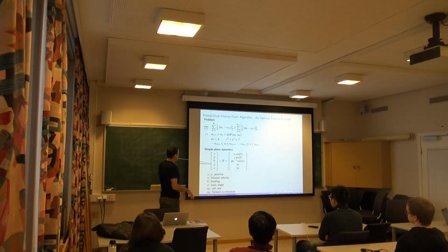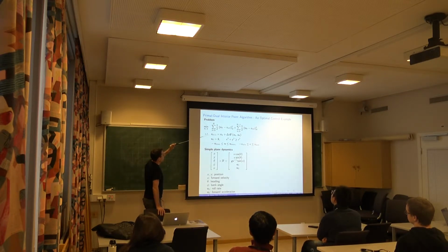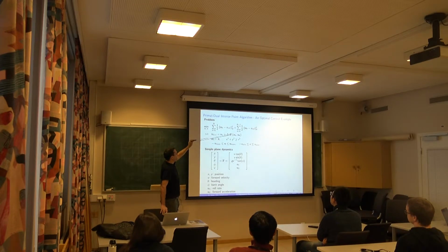And no, sorry, theta is the orientation, theta is the heading, and phi is the bank angle. And you can control the velocity as well. And just to show you that in principle you can solve problems doing very basic things. For example, here I'm discretizing the dynamics via a simple Euler integrator. We discussed integrators and very advanced techniques to process the dynamics.